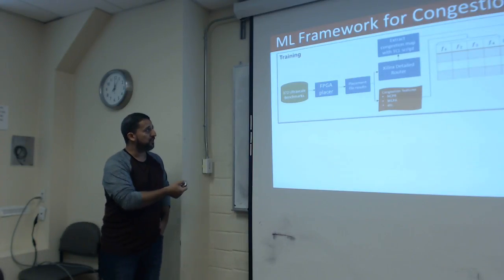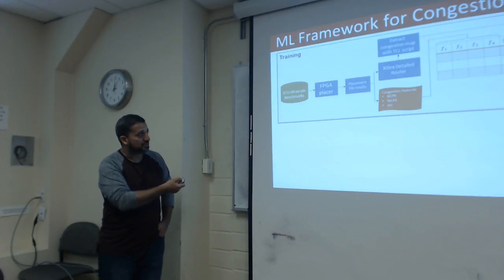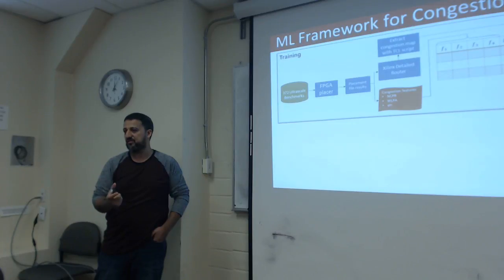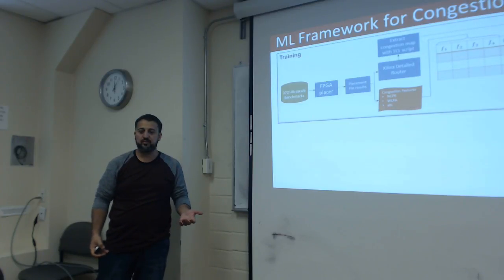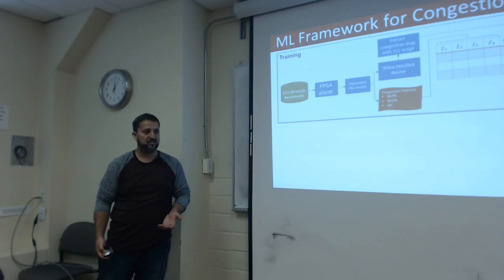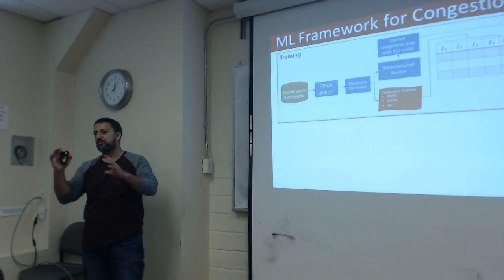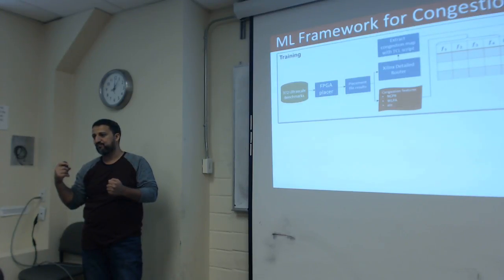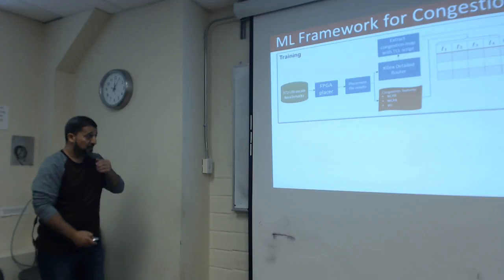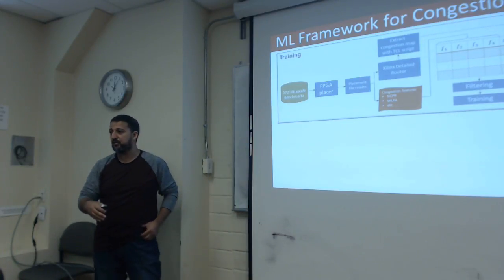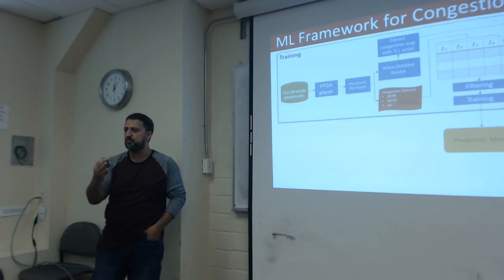Another thing is, after we extract and have a congestion value for each, we use it as a label. Each row in the data set is a switch box. We are dealing with fine grain when we do the training, so you end up with maybe 28 million records in the data set. We're not taking that into a complete picture, but we use those features to capture some global information. And at the end we do some smoothing to get global information from neighbor switches. We filter by taking off the switches that are not used by the router, so it's not confusing the model. Then we train with different models, but we end up using a linear regression model.